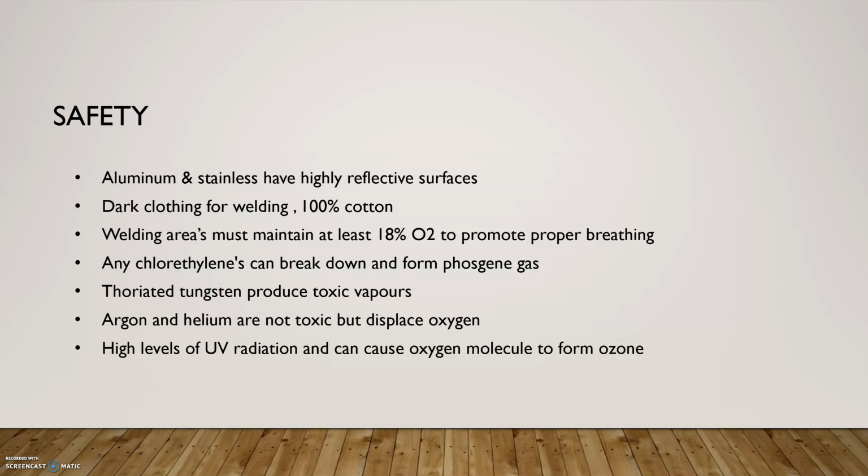To promote proper breathing, areas must maintain a very minimum of 18% oxygen. But if it was me, I'd probably be concerned at 18% oxygen.